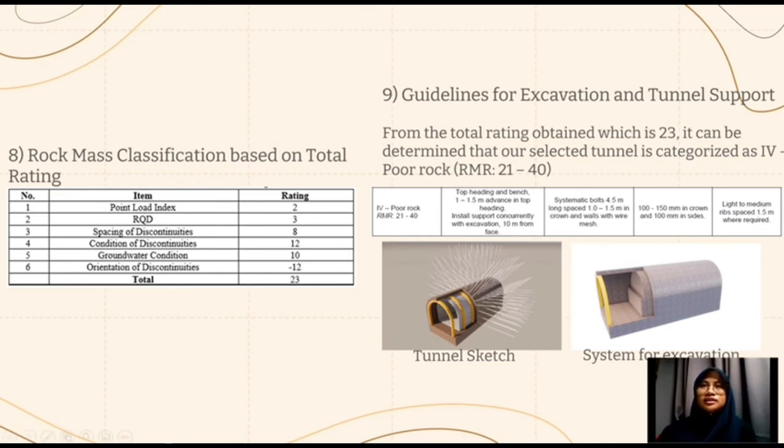in this table. So, in order to implement the field research, the walls of the tunnel through the poor rock must be formed in a wire mesh, and the rock bolts supporting it must be 4.5 meters long and spaced 1 to 1.5 meters apart in the crown. If shotcrete is used to support the tunnel, the crown and sides must each have 100 mm of shotcrete.